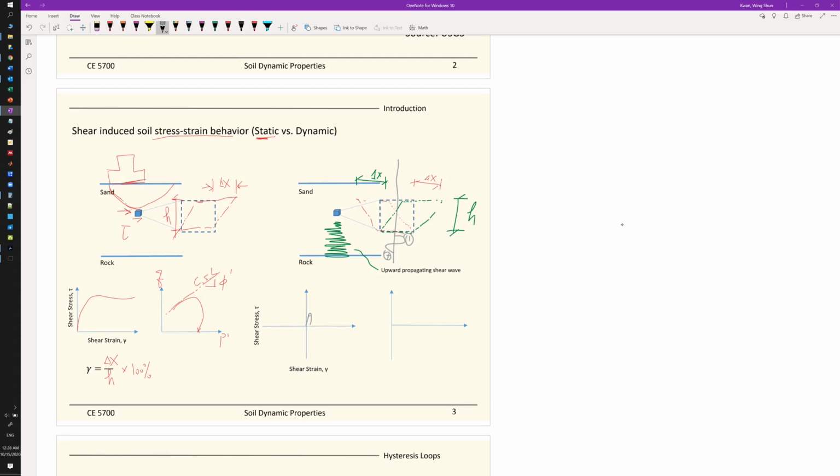And then you go up, go down, and then go to the negative, and then you would generate negative displacements too. So this is kind of like the hysteresis loops for the stress strain part under cyclic loading. And assume this is your first loading cycle, and then there are a bunch of different loading cycles going through the soil elements that you're looking at.